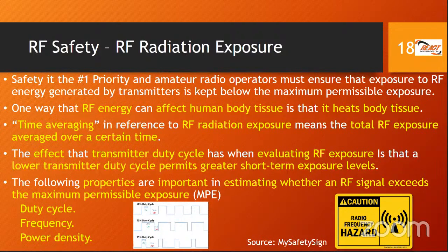So you don't want to be in front of a magnetron, which is what the microwave ovens are based on, because it will heat you, it will cook you. So it's the same thing with RF energy. You need to respect all forms of RF energy because it has the potential to do that. That's why we say don't go touch an antenna while it's transmitting. Don't go too near. You have exposure limits and you have distances that you need to keep.